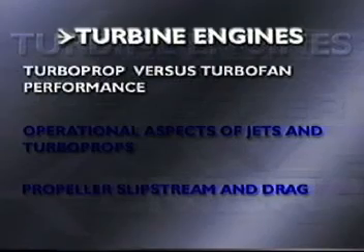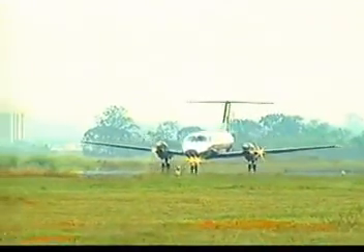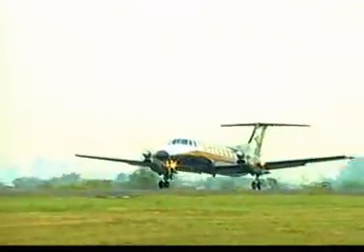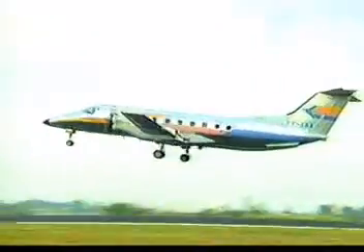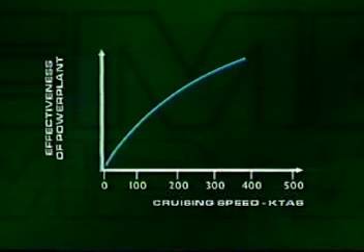Turboprop versus turbofan performance. Because of the propeller reduction gearing and the intricate propeller governing feature, the turboprop engine is heavier and more complicated than a turbofan engine of equivalent power. However, the turboprop performance during takeoff and climb is remarkably greater than the turbofan engine as a result of the ability of the propeller to accelerate a large mass of air at low flight speeds. But check what happens with the propulsive efficiency in the chart and see what happens when airspeed increases.